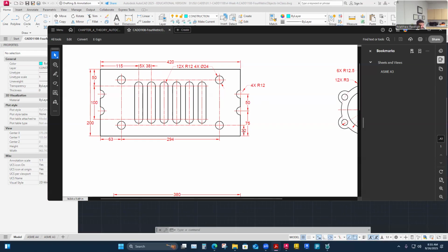And so I can start to infer some things here, mainly because these holes have absolute center line alignment shown. That allows me to say this is 32 to this one, that means this is 32 to this one. This is 63, this is 294. So I do get the placement of these. The one that's a little bit vague is in between here.